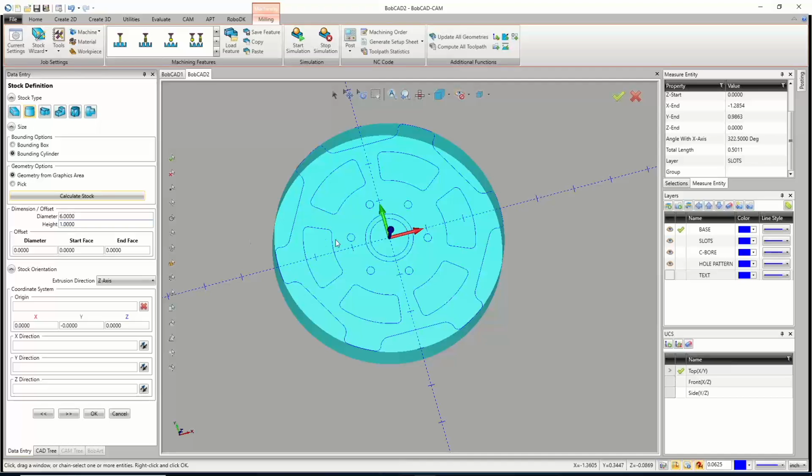It gives us the same result here, but it's a better option because it fits to the full shape, not the center of a square. So just so you know. Or if you ever have odd shaped stock, like you just had one of these instead of a whole thing, so the rest of it would be this diameter here and one little bump out, you'd still want to use a round piece of stock, centered fully. So there we go. So it finds the full stock for you. That's all I'm trying to say.